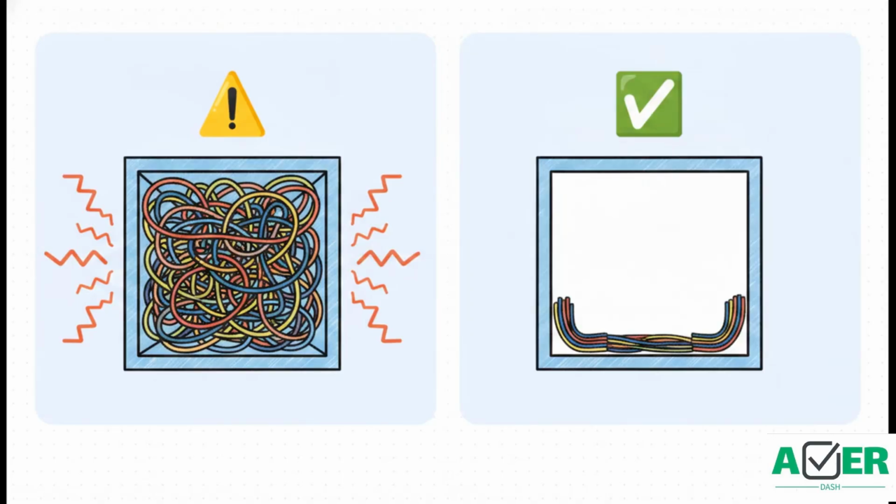Now, just look at the massive difference between an overcrowded cell choking on cables compared to a super clean, code-compliant arrangement. Signal and control conductors, like your Class 1 or Class 2 circuits, absolutely need physical space. Rule 12-1802 strictly dictates that, generally speaking, you cannot mix different systems in the exact same cell. Jamming way too many cables into a hollow header creates a massive physical choke point. It makes maintenance virtually impossible and introduces some really severe safety hazards.